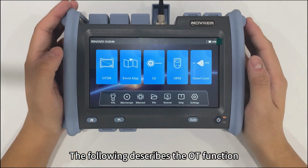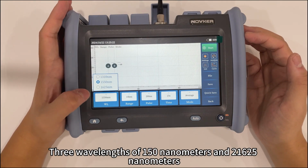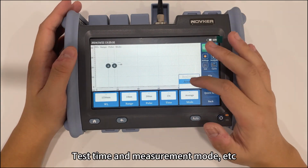The following describes the OTDR function. In turn, we can choose the test wavelengths. This device has 3 wavelengths: 1310 nanometers, 1550 nanometers, and 1625 nanometers. Then the test range, pulse width, test time, and measurement mode, etc.